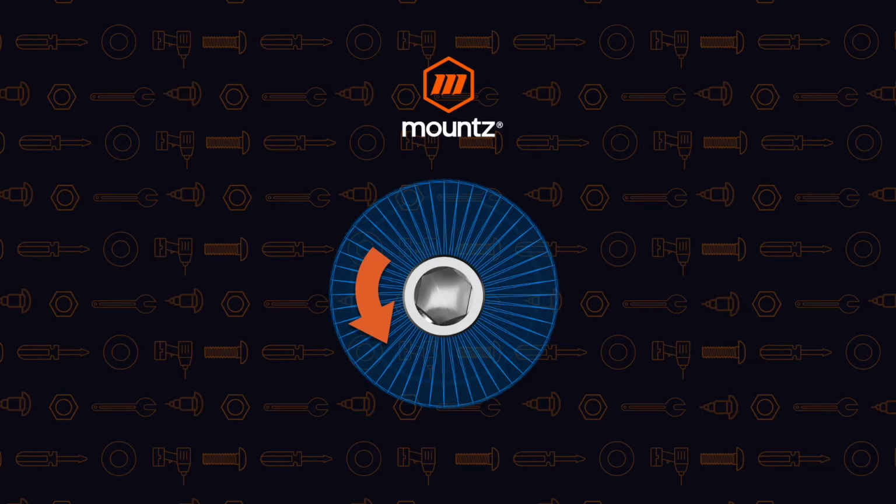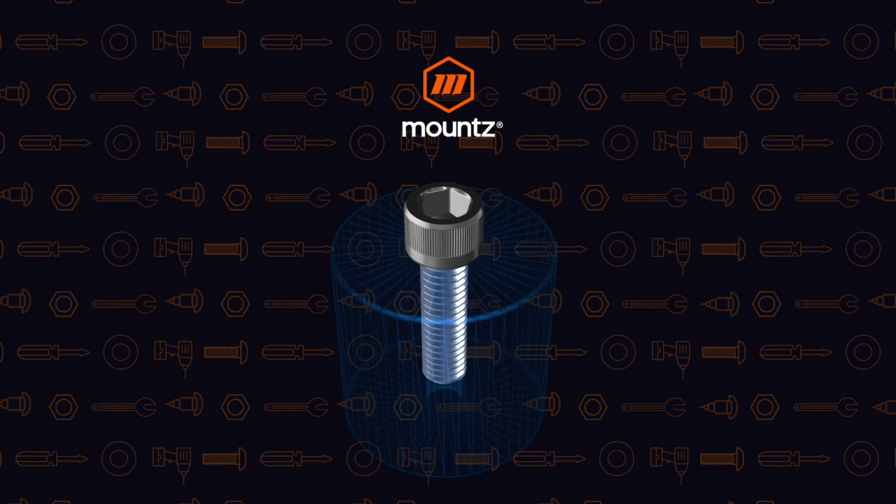So if we again mark the part and the fastener, and then we go ahead and break the fastener loose, and then come back and retighten it, that will give us a very similar torque value to what the fastener was initially torqued at, minus any changes in the coefficient of friction based off of materials, or any lubrication that was used. And so that coefficient of friction may change depending on the materials.